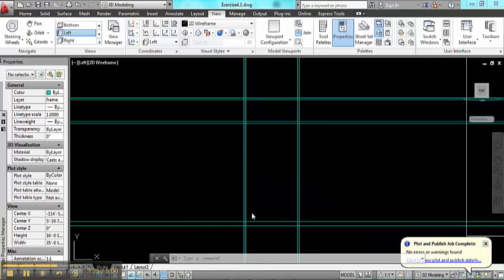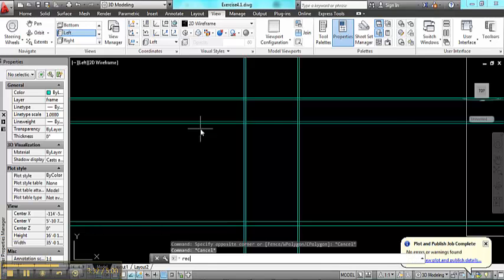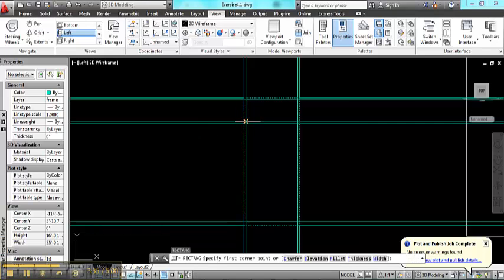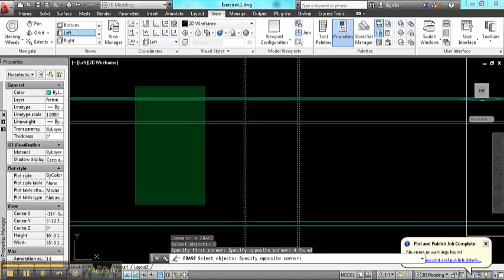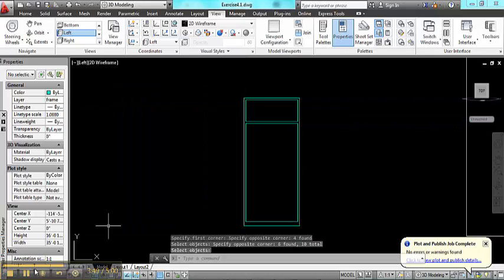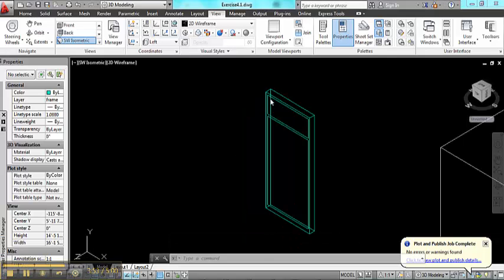Here I am looking at the frame from the left view, and what I'll do is I'll make rectangles at these intersections. So I type in rectangle, and then I snap to here, and here, and to here, and here. Then I can erase the X lines. Don't need them any longer, like so. Now I'll look at it again from Southwest view. So from Southwest view, you can see the rectangles that I just constructed, and they're drawn on the surface of the box.